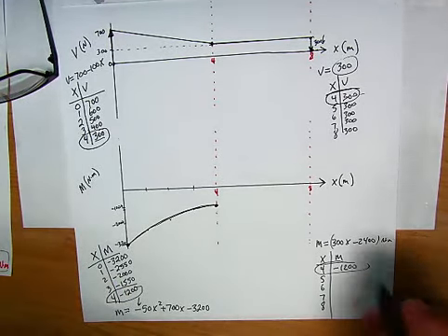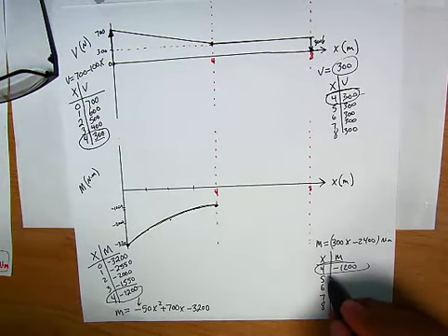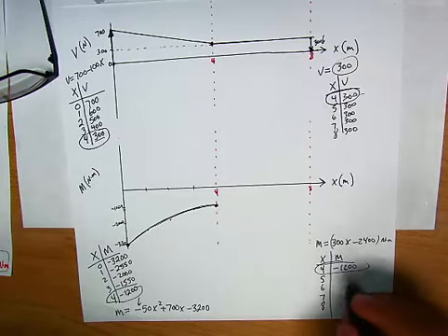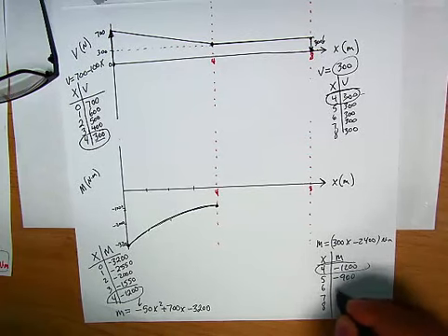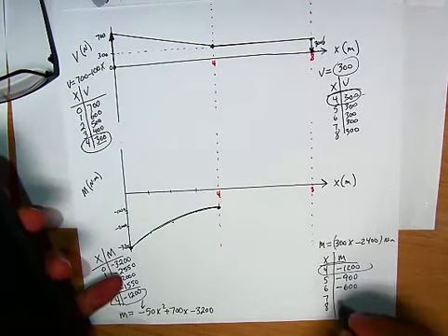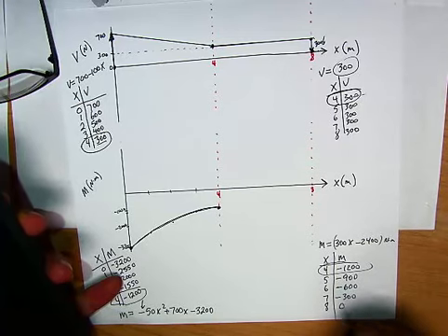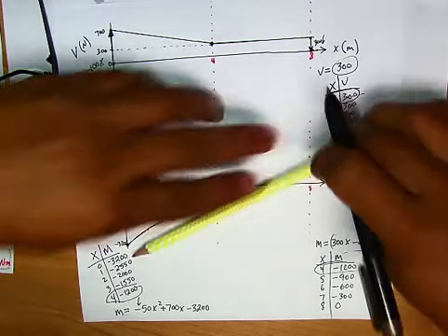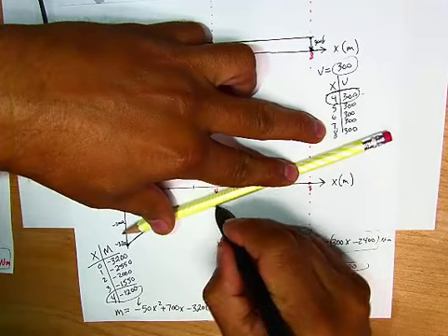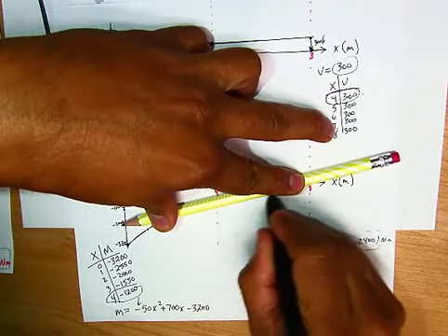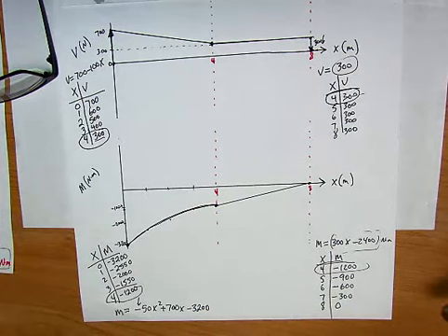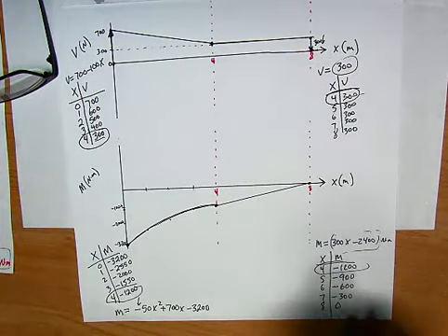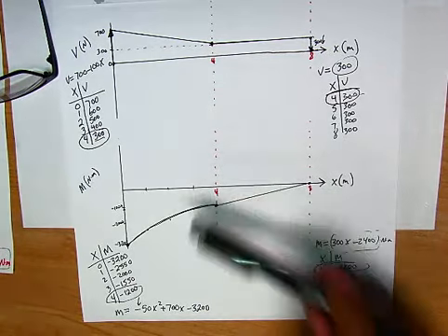That's pretty neat. So to this, we're going to be adding, basically, since we're starting at negative 1200, our slope is 300, we're going to be adding 300 every time. So negative 1200 plus 300, negative 900, negative 600, negative 300, and 0. So this is a linear graph. It's a line, and that one goes straight from here to there. Not the straightest of lines, especially working at an angle. So there you have it. This is your shear diagram, your moment diagram.